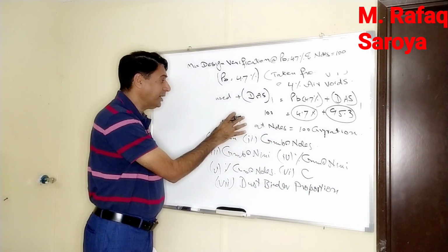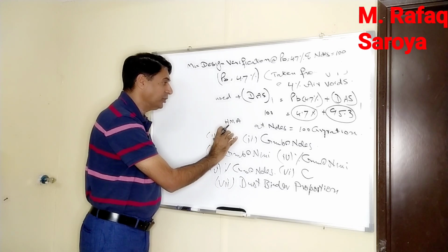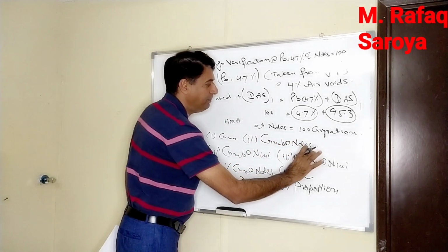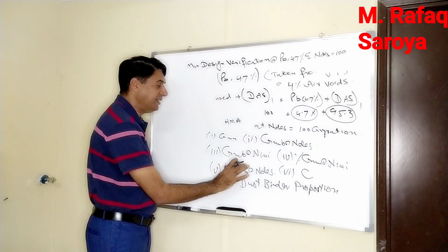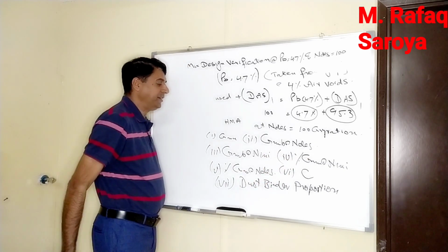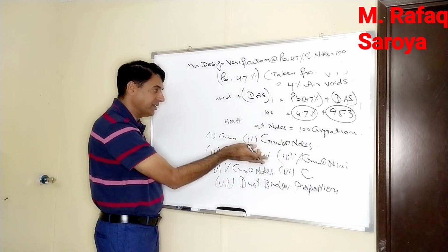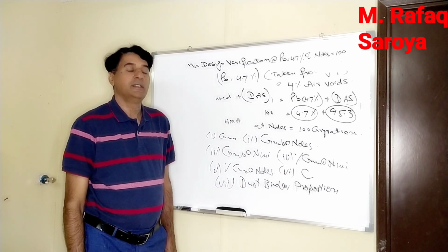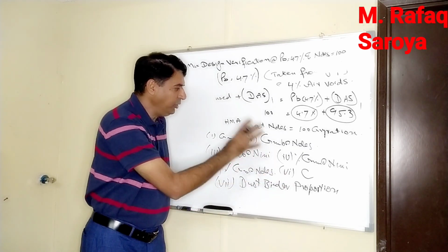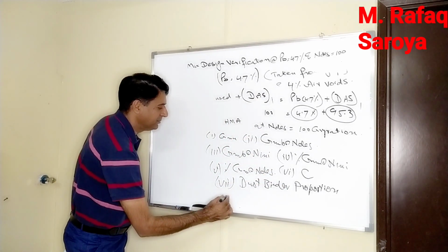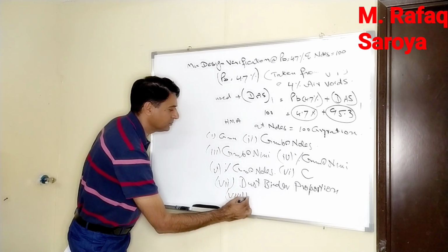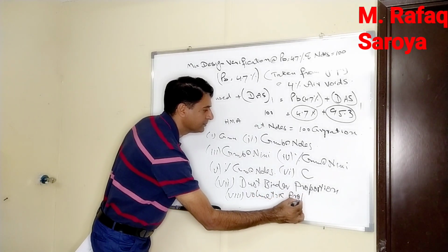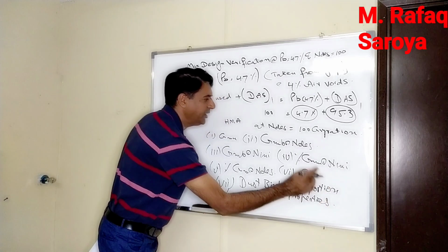So from this hot mixed asphalt which has been developed, we have to find out the GMM, the GMB at N design, the GMB at N initial, percentage GMM at N initial, percentage GMM at N design, then C, the correction factor, because this correction factor is for making the relation, then the dust to binder proportion. Clear? Similarly, by knowing these other volumetric properties, these are our requirements.